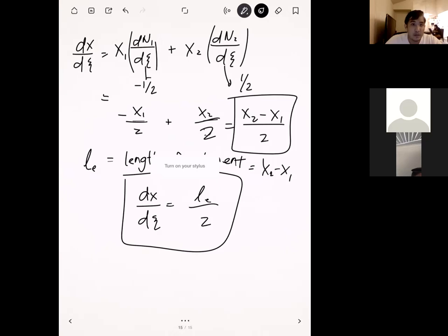Yeah, I think that's true. Normally the bike crank does rotate like that. But for this particular problem, we were looking at just the bike crank right before it reaches that rotating part. The rotating part is kind of a different part of the bike. But you can definitely argue that you can use a pin support too. I think the problem is that for the hand calculation part, if you use a pin support, you wouldn't be able to find a solution because there's nothing there to restrain the rotation. And so you might get an infinite rotation there.